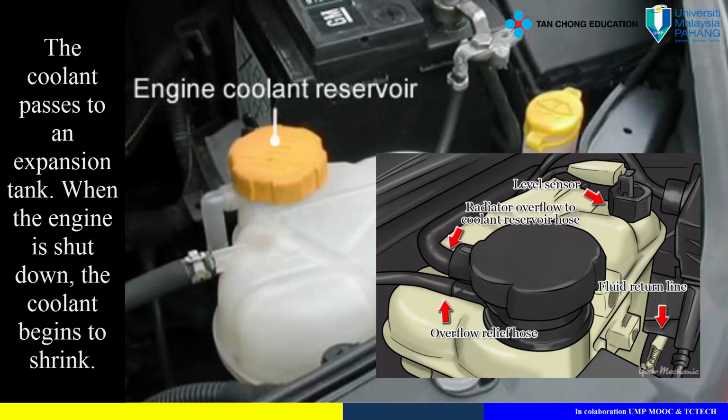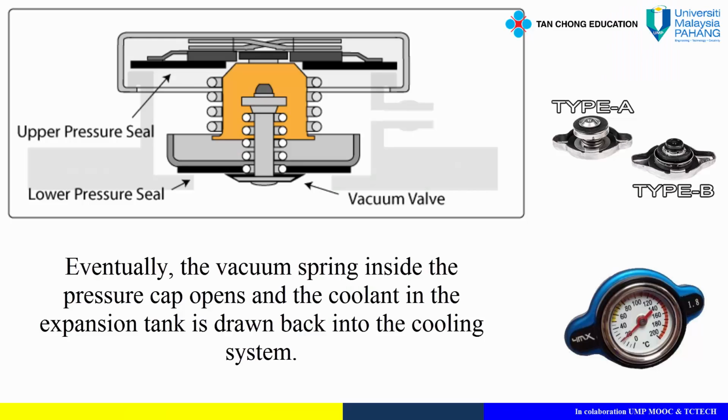When the engine is shut down, the coolant begins to shrink. Eventually, the vacuum spring inside the pressure cap opens, and the coolant in the expansion tank is drawn back into the cooling system.